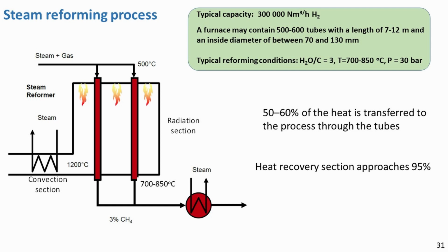Typical inlet temperatures to the catalyst bed are 450–650 degrees C, and the product gas leaves the reformer at 700 to 950 degrees C, depending on the application. The average heat flux from the burners may be larger than 150 kilowatts per square meter, and tubular reformers operate at a high mass velocity corresponding to a Reynolds number larger than 5,000.